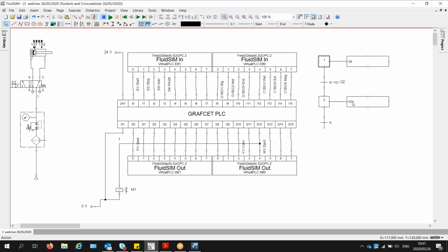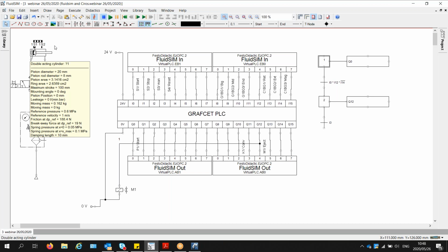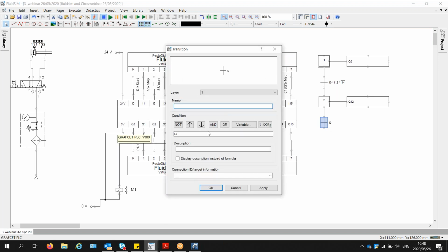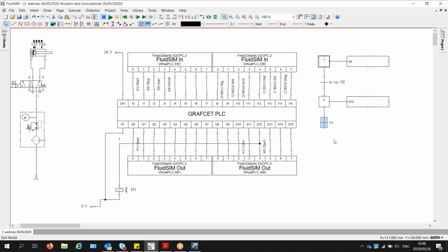Now we're at a point where we turn on the output number 12, which is eject a workpiece. Now, when ejecting a workpiece, obviously 1S1 will turn off and 1S2 will turn on. And 1S2 here, we denoted it by C1BG2, which is input 13. So here I need to change this to 13, so that we verify it, so that we jump to the next step after the cylinder is fully extended.